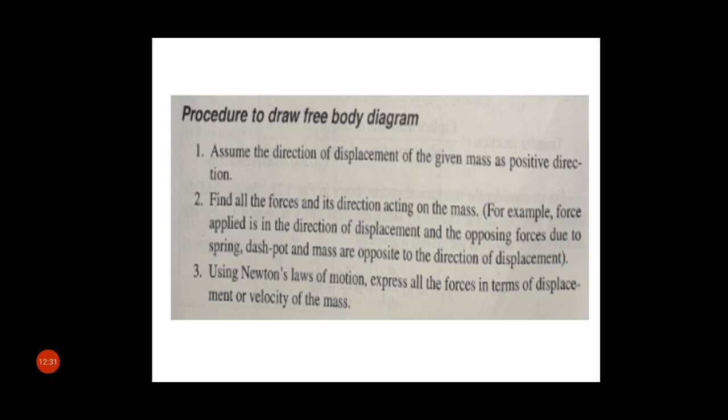To obtain the mathematical model of a mechanical system, it is necessary to draw a free body diagram indicating the various forces acting on it. In a free body diagram, each mass is considered separately with all forces acting on it.